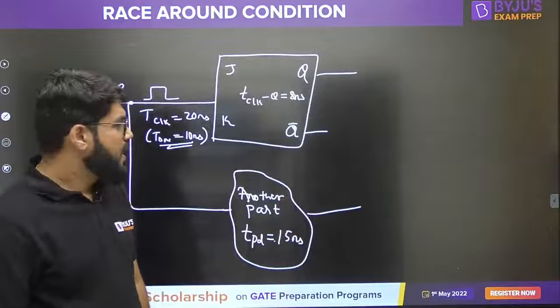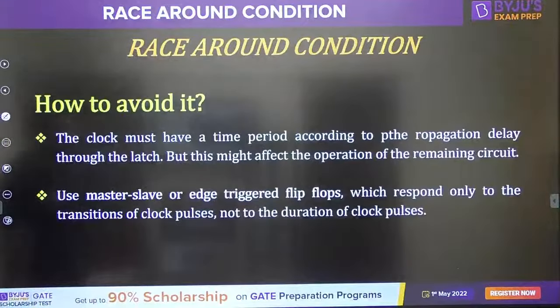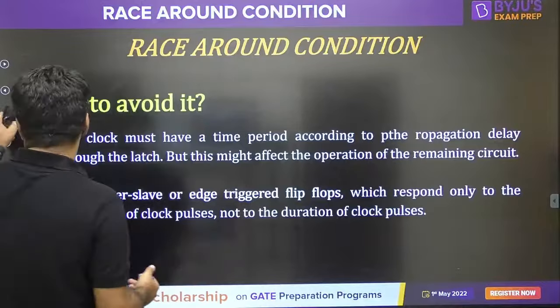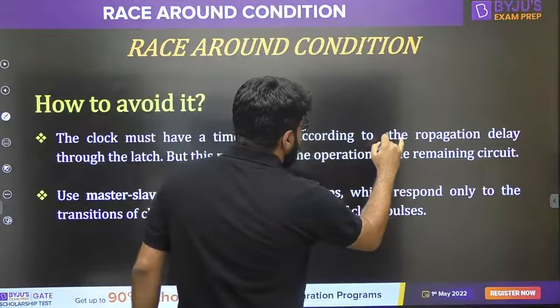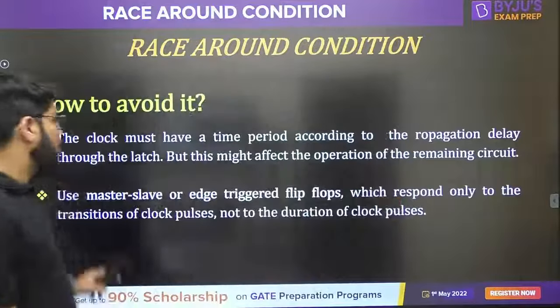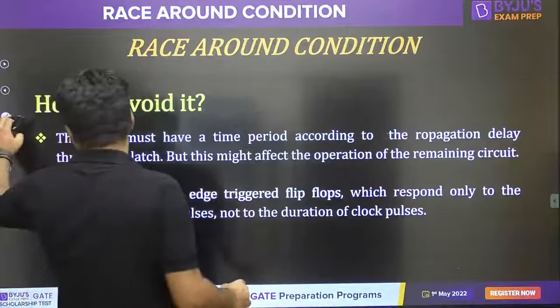Okay guys? Look into these possible solutions. How to avoid this? The clock must have a time period according to the propagation delay. The latch must have, the clock must have a time period according to the propagation delay.